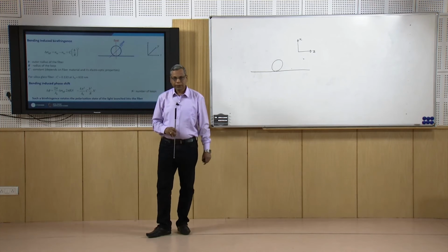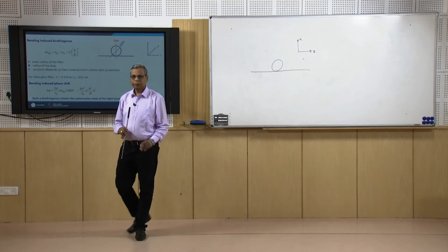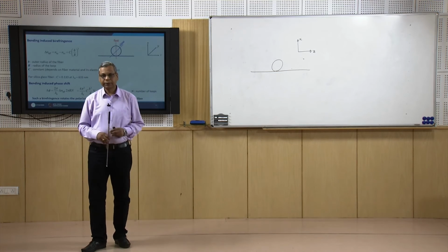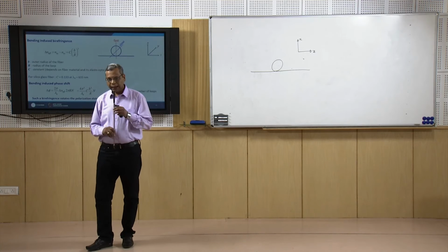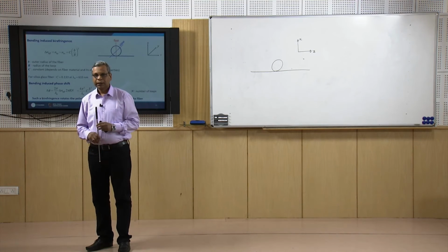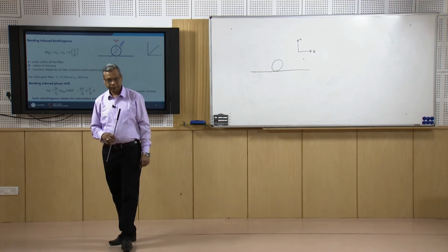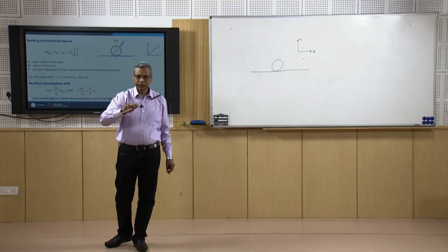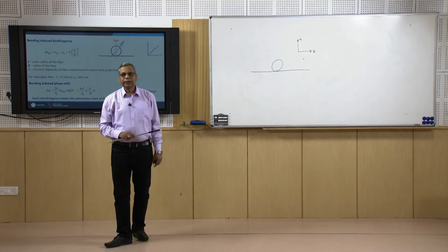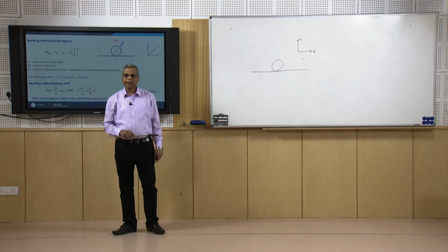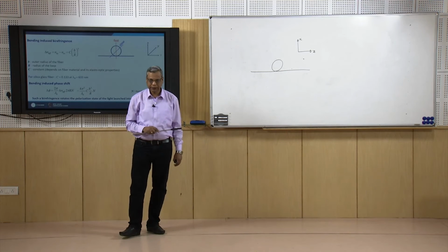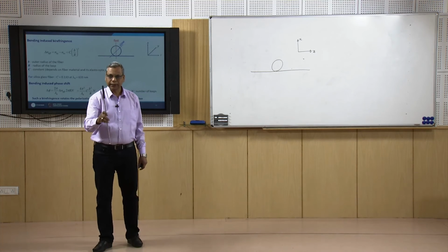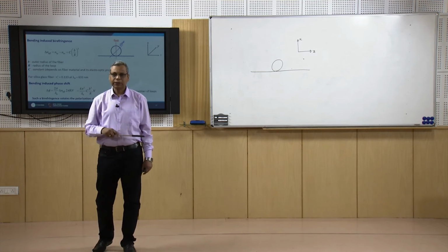Now, if at the input end of the fiber you excite both the polarizations simultaneously, then as they propagate in the fiber, a phase shift would be accumulated between them, and the state of polarization at any value of Z inside the fiber can be found out by superposing these two polarizations with the accumulated phase shift.